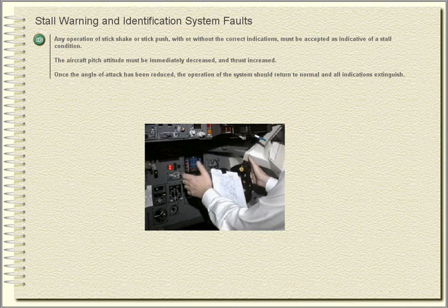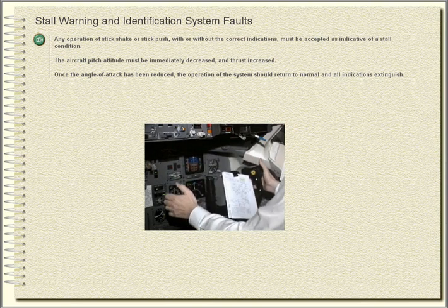The aircraft pitch attitude must be immediately decreased and thrust increased. Once the angle of attack has been reduced, the operation of the system should return to normal and all indications extinguish.